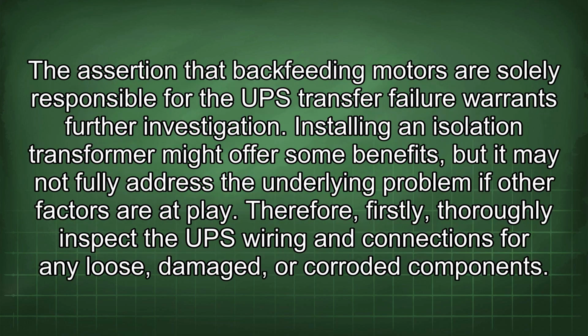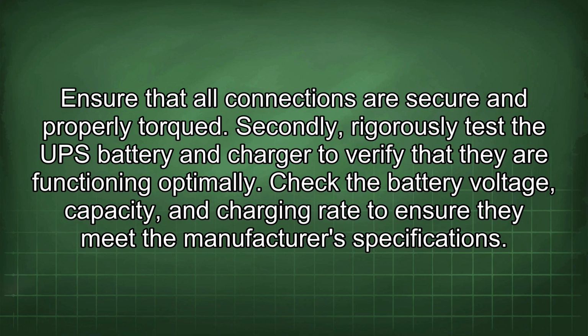The assertion that backfeeding motors are solely responsible for the UPS transfer failure warrants further investigation. Installing an isolation transformer might offer some benefits, but it may not fully address the underlying problem if other factors are at play. Therefore, firstly, thoroughly inspect the UPS wiring and connections for any loose, damaged, or corroded components. Ensure that all connections are secure and properly torqued.